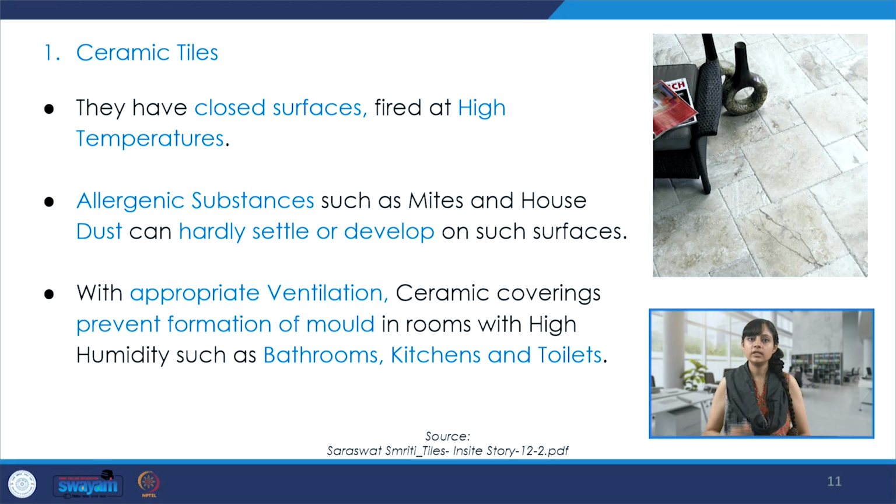Now, when we talk about the types of tiles, there is a lot of variety, but talking about the major ones that one could find in the market and which are popular, we could start by understanding the ceramic tiles. Now, they have closed surfaces which are fired at very high temperatures, and substances like mites and dust can hardly settle or develop on such surfaces. With appropriate ventilation, ceramic coverings prevent formation of mold in rooms with high humidity, such as bathrooms, kitchens, and toilets.